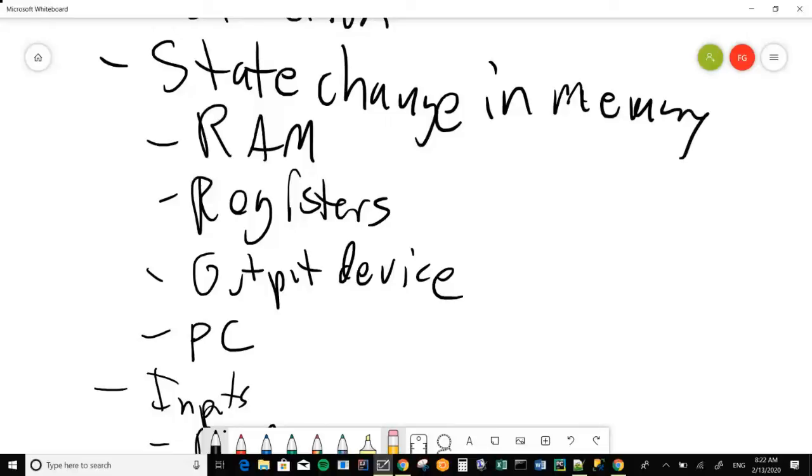Distinct is the notion of CPU registers. So CPU registers are essential for helping guide the CPU to actually do something. As we saw, for example, many instructions depend on the notion of an address. That is, where in memory, whether it be program memory for a jump or data memory for reads and writes, where in memory is this going to have an impact? In this CPU design, we need the A register in order to specify these things.